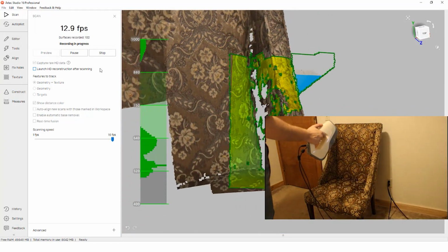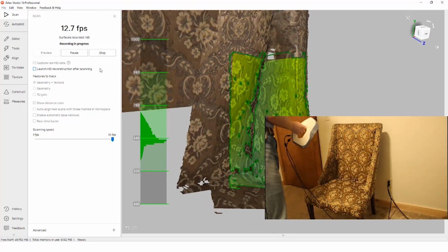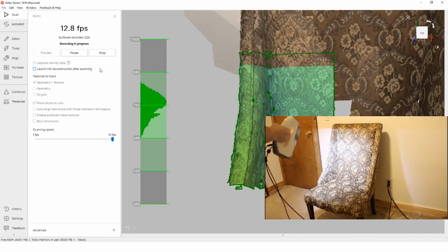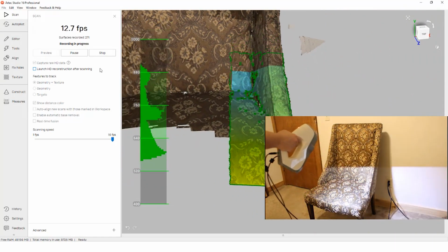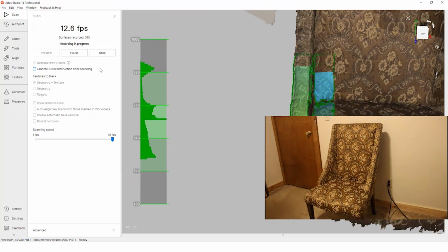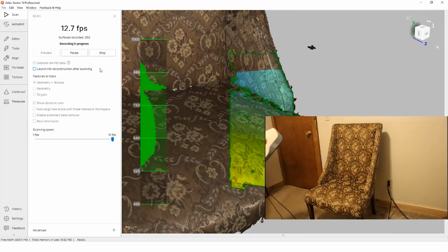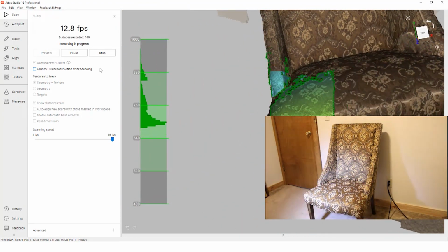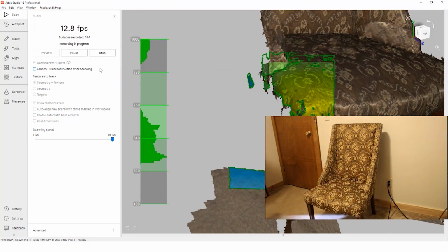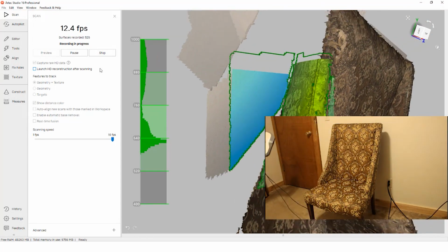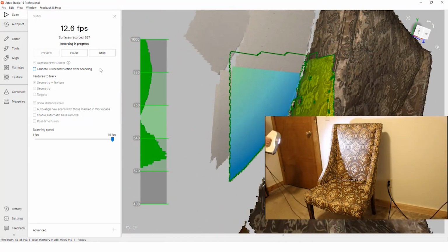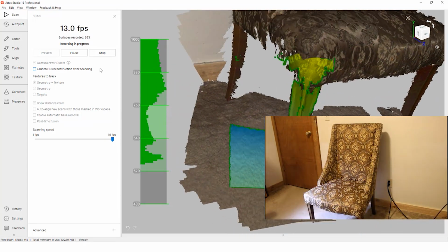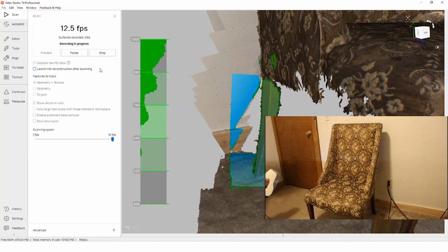Pressing the Start button again will actually start capturing the data. The data being shown is now staying longer and our histogram is being displayed on our scan. We'll keep an even distance and move around the object kind of like spray painting it. And I'm keeping an eye on my computer screen, not the object, to see if I'm missing any spots in the data. The scanner is constantly capturing data. The FPS number indicates how many photos we're capturing at a time. If you stay in one spot, it'll repeat the data, leading to larger file sizes. So try to map out a path you want to take to get all the spots on the object.